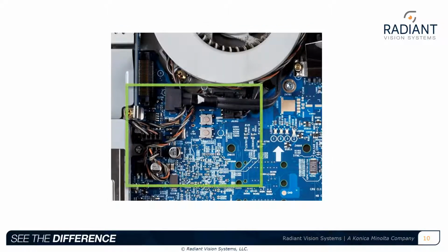Latent device failures can also result when components are pinched or broken through repeated use of a device. This can happen when components aren't installed in the appropriate positions, or when the internal components are closed in the device housing. Misplaced components like misrouted cables may come into contact with other components unintentionally. Hinges may pinch a cable as a device is used, or a hot battery in contact with a cable may melt the plastic, causing a failure down the road.